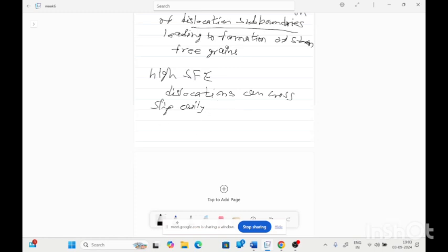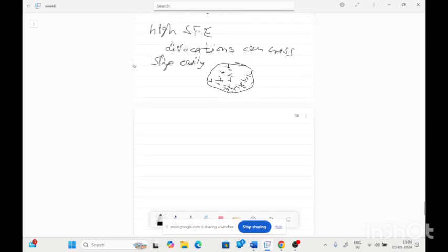During the deformation, dislocation density increases, and those dislocations cross slip and form the sub boundaries in a single grain. This is a single grain, so the dislocations arrange in some manner and form this type of regions. These regions and their boundaries are called the dislocation sub boundaries.